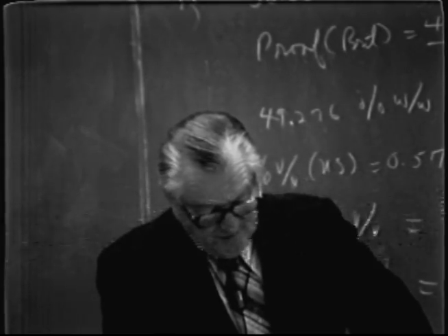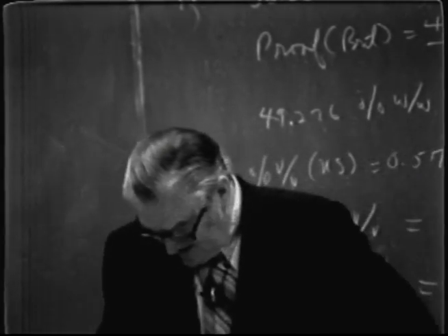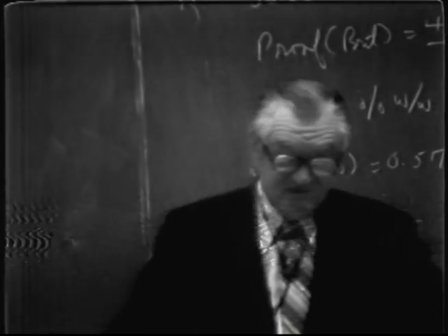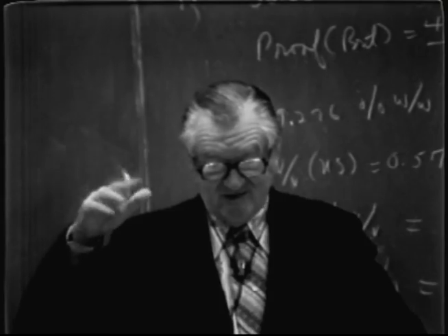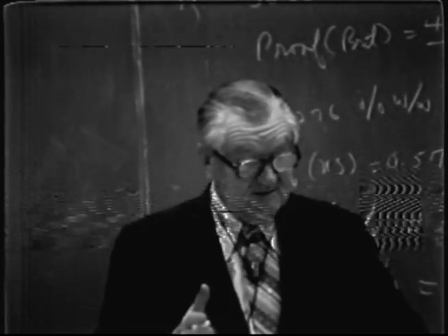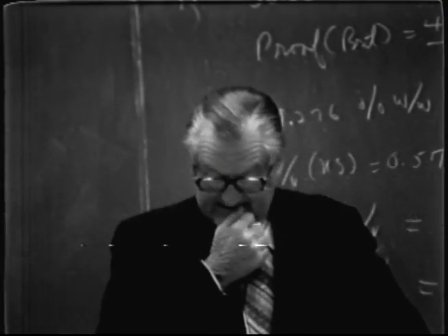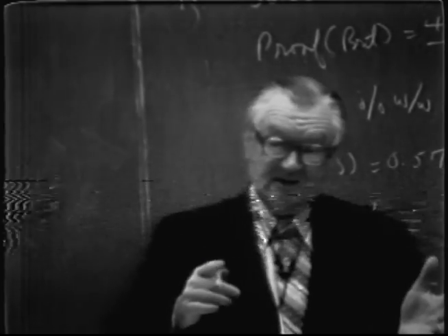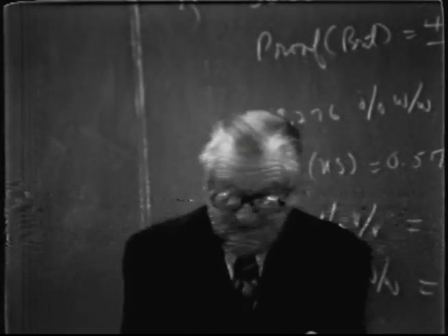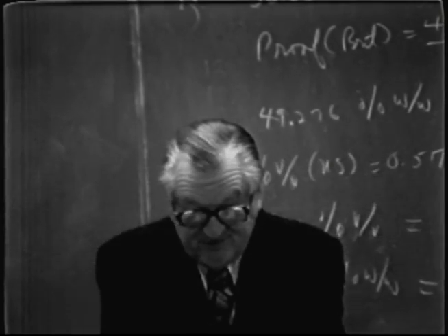Then the total number of pound moles per hour of feed would be the sum of the pound moles of alcohol, in other words the pounds of alcohol divided by its molecular weight, plus the pounds of water divided by the molecular weight of water. That would be the pound moles of feed. In which case, you could do it without any tables. Find what the weight percent alcohol in the feed is, and multiply them.